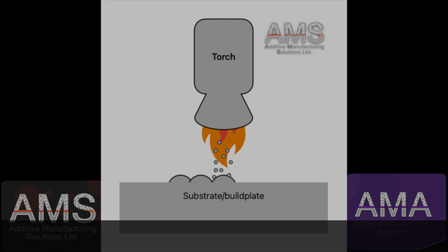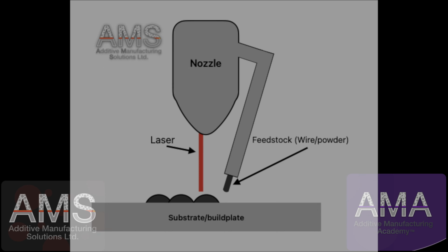In the case of direct energy deposition, or DED, with a powder or wire and a laser beam or an electron beam, we are looking at a full remelt. So in these instances, the material is added at the source of the energy, electron or laser beam. The material is fully melted and solidified rapidly.